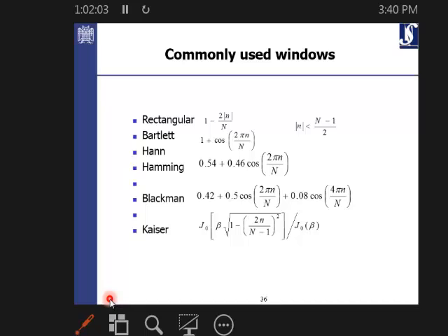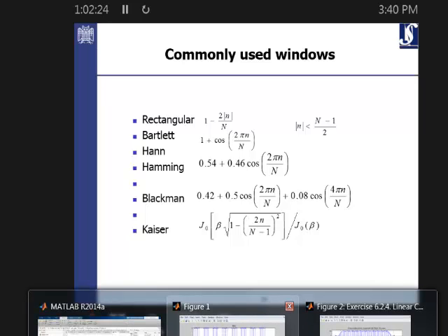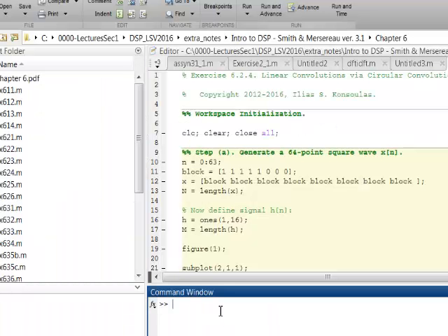So you have an ideal low pass filter, you design it, you set it up, then you say, okay, what kind of window do I have to multiply by that ideal filter to get the FIR filter as an equivalent in the output. And these are the types of the windows that you can have. But let me go through the software to see exactly what happens.